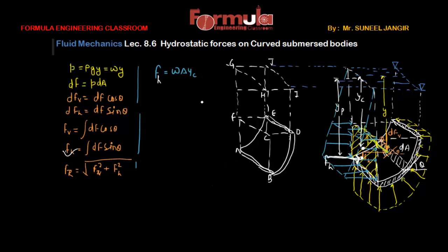Okay. So in this case, we want to calculate the vertical force. The vertical force will be equal to the weight of the fluid held by this curved surface above it. Obviously in this case, this much volume of fluid is being held, so I think we can calculate the weight of this fluid.